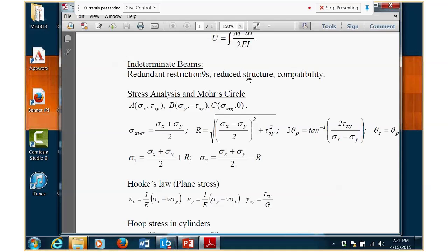Okay. And the compatibility, right? Remember we always say FDC, the F part, the free body diagram, that's the same, right? The equation of equilibrium remains the same, right? The deformation equation, actually, you can find from the table. And the key will be compatibility. So compatibility here is basically a boundary condition, right? It sounds very abstract, very theoretical, right? But actually, that's what we're doing. So you find the compatibility, that's a boundary condition. Okay, because it's so abstract, we'll go over maybe a couple more examples as well.